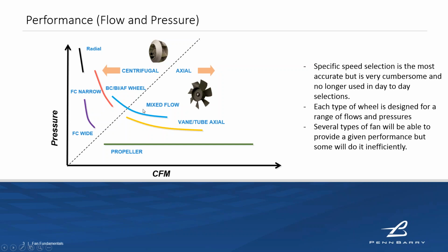And bridging the gap is mixed flow fans. Mixed flow fans have been around for 20, 30 years, but they're becoming more and more popular as they're a nice sweet spot between the characteristics of a centrifugal and an axial fan, and they have really nice sound characteristics. So that's where we see a lot of the inline ducted market moving toward.